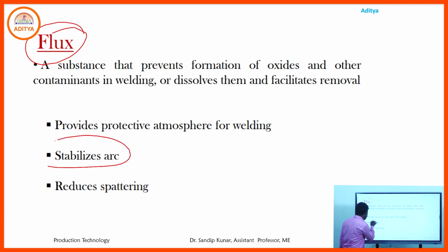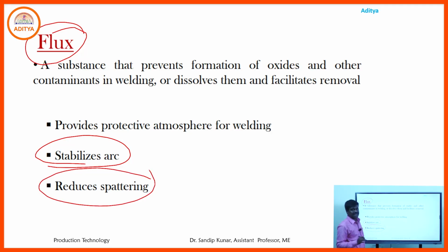Another function is to stabilize the arc between the work surface and the electrode. It also reduces spattering. Sometimes during welding, spattering causes extra metal to accumulate on the weld surface, so we use flux to avoid these things.